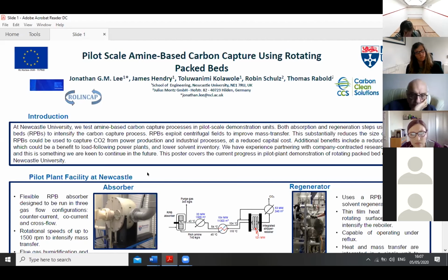Corrosion rates and things, not really. I know the material we use in the machine is compatible with the amines. Yeah, even with stainless. I mean, we've seen that practically at 40% MEA, which is the highest concentration we've used in a conventional absorber. Is that because of its corrosion? I don't know. It just seems to react a lot quicker with stainless steel. That's all. Under those conditions, you know, as you increase the concentration.